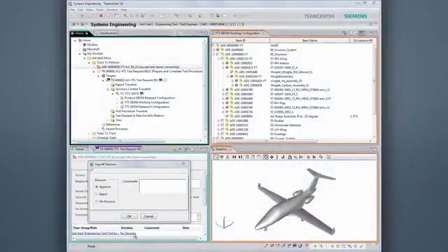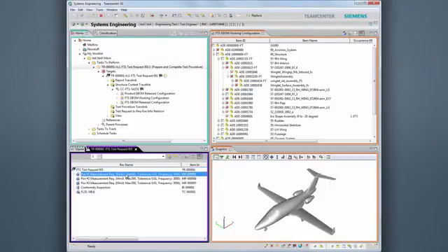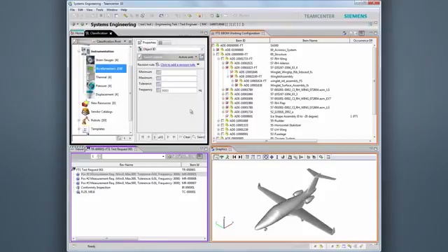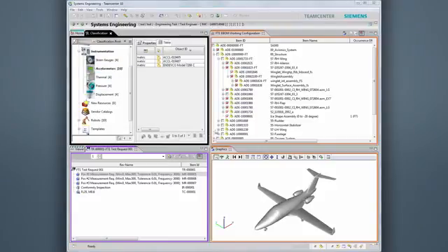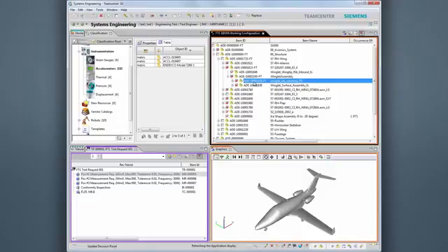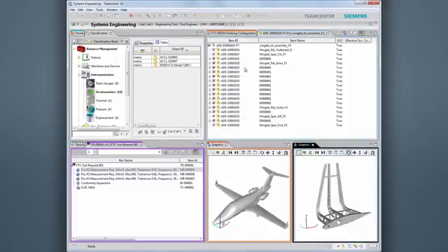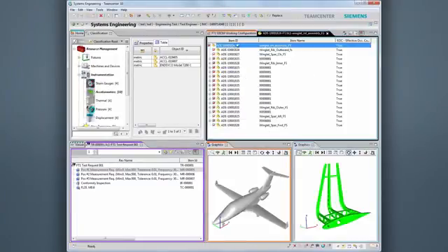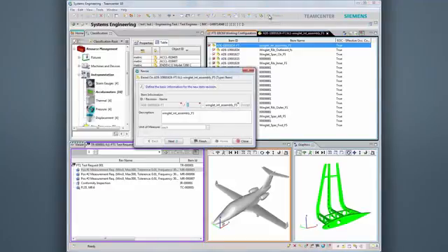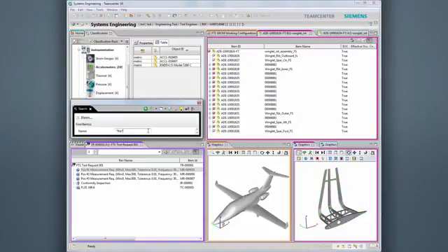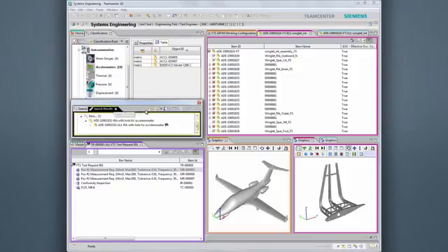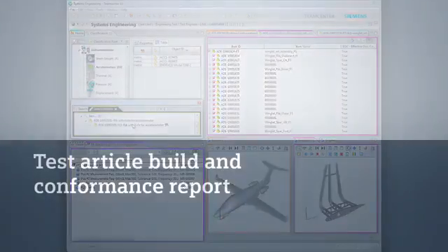After receiving the test request and accepting ownership of the test article EBOM, the test engineer searches in the classification application for the instruments that match the specifications that are identified in the measurement requirements. In this case, 3 accelerometers match the frequency of 3000 Hz. The winglet assembly gets revised and the original rib is replaced with a new rib containing holes to accommodate accelerometers.